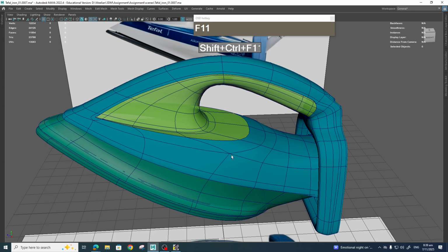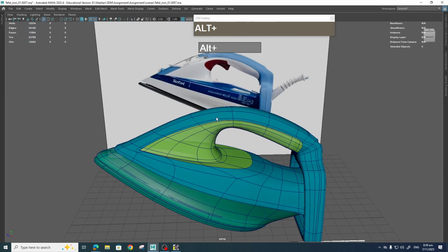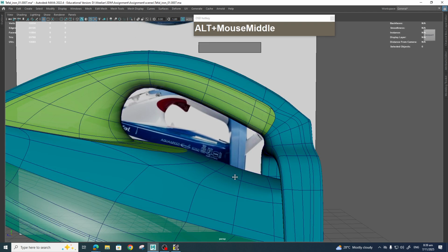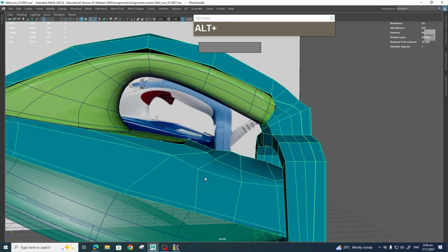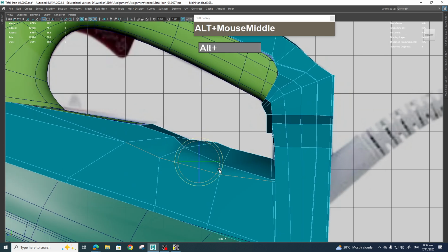Alright, so continuing from where we left off, looking at this shape and then comparing to the reference, we notice that there's a very hard line over here, a straight edge. So that means I have to insert another edge loop that runs across the edge loop around here. By looking at this, we realize that at level 1, we want these lines here to be as straight as possible. So what we're going to do is go to level 1, select this edge, then use a scale to scale them down. Unfortunately, Maya doesn't have a skew function, so we have to do it this way.